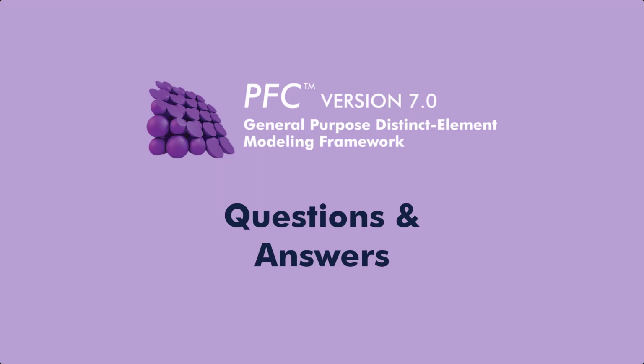It's doing a discrete force displacement law where relative displacements are causing forces, but then it's saying, well, hey, what's the stress on the particles that are in contact? And if I have that stress state, what additional forces would I need to add to get me to the correct Poisson's ratio based on continuum theory, right? And this really gives you a very nice continuum-like elastic response. And as I said, also removes the grain scale heterogeneity in elastic response. So I think these are really powerful tools for bonded block or bonded ball SRM style models.